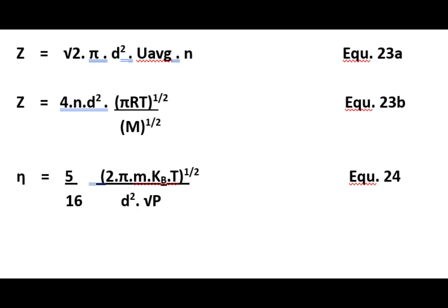The more frequent the collisions, the more likely energy and momentum will be transferred between molecules, affecting these transport properties. Equation 23 shows the collision frequency of gases, which is directly proportional to the square of the molecular diameter, d, average velocity, WAVG, and number density of molecules, n.